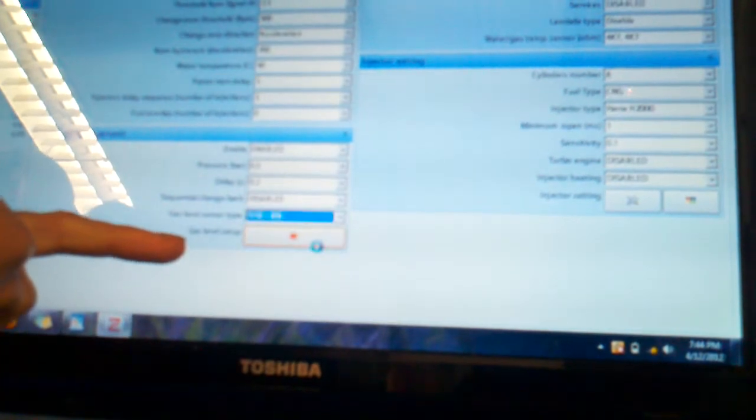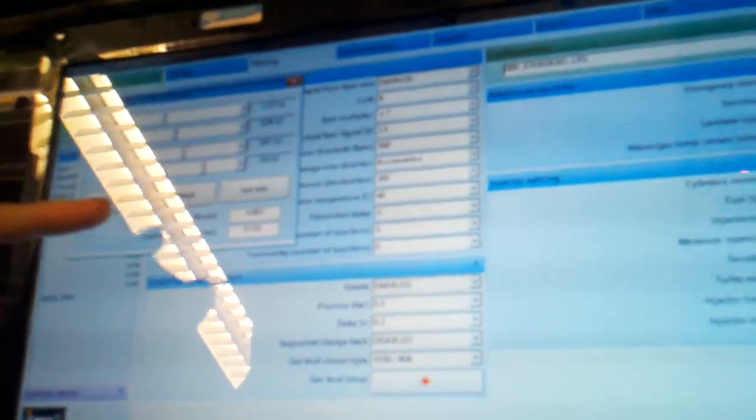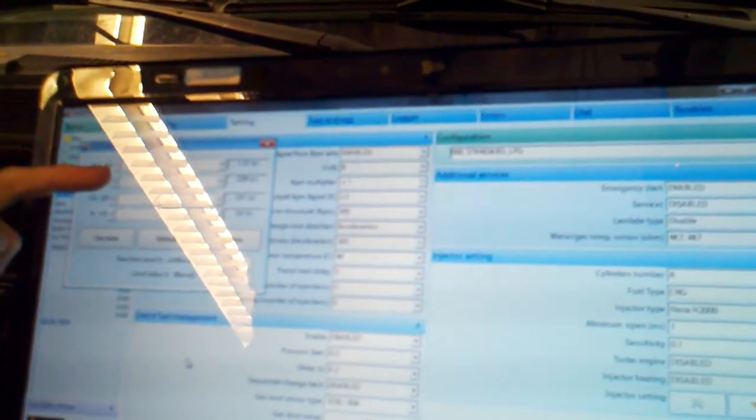The manometer that we have, gas level sensor, is an 806, I think. Yeah, it's an 806. So we want to select that. Then we can actually go in here, Wayne. Yep. This is what I was going to show you on the other. Exact same type of thing. Our current setting, real-time value, is 4.8 volts. Filtered value, 0.195, 0.2. Something doesn't seem right there.